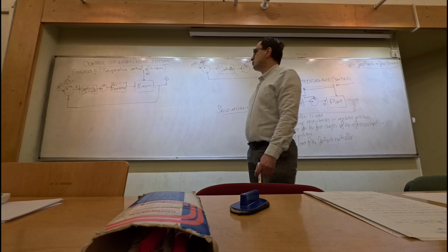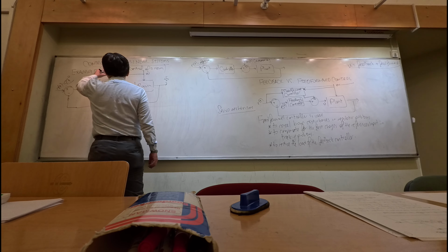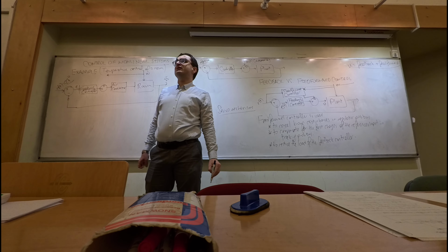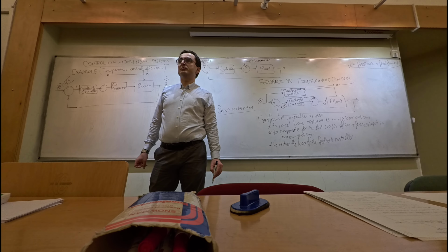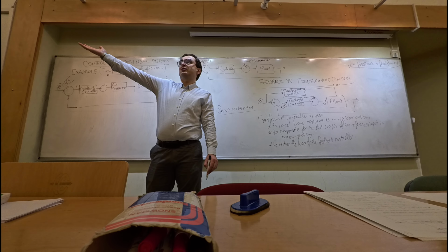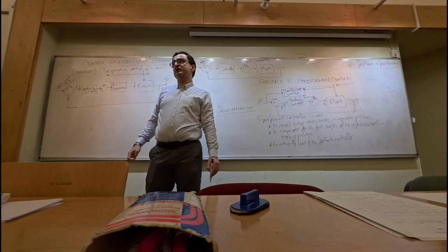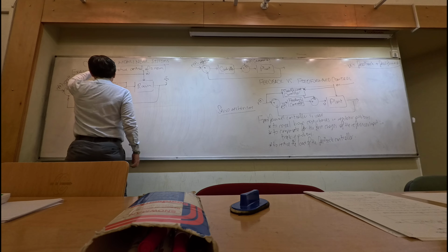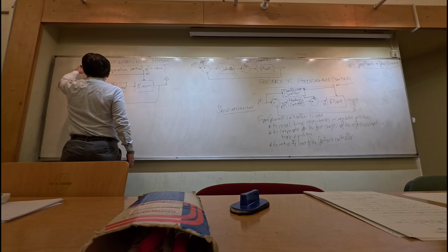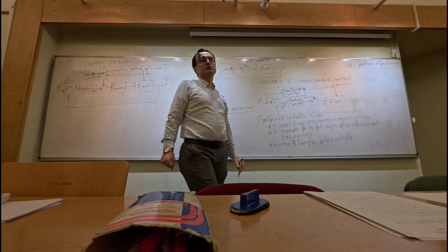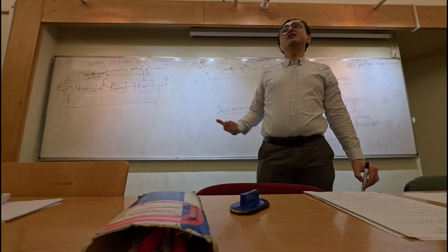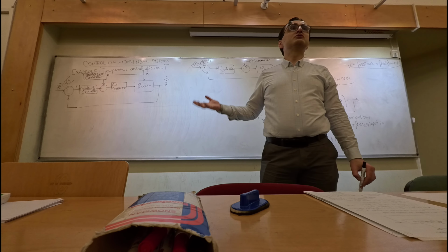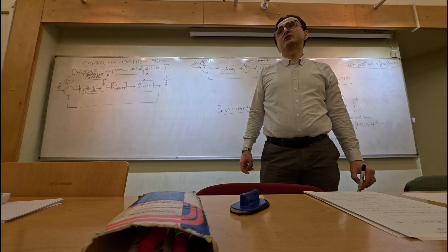If we really do not want to do this, we can actually use a feed-forward controller there. So, for example, what we can do is try to measure this disturbance signal. So we will know what is going to be the temperature outside before there appears an error in this system. We will put a temperature sensor outside, maybe, and then we will measure this disturbance. So by measuring this disturbance, a feed-forward controller can start heating the room before it actually cools down, and before an error actually appears in the system.